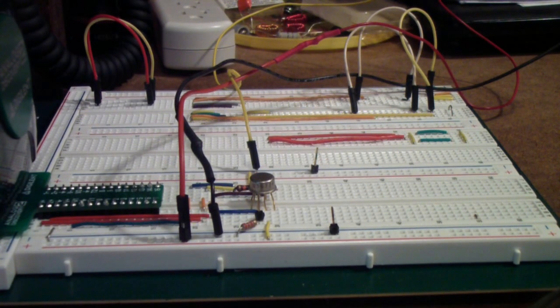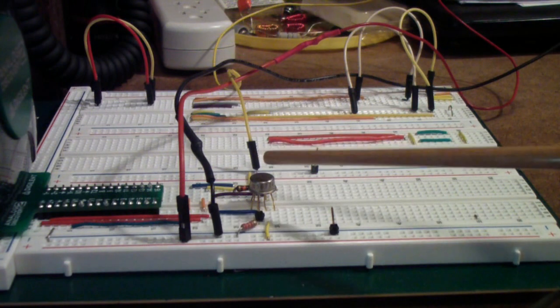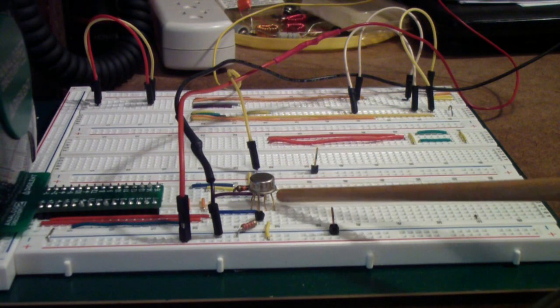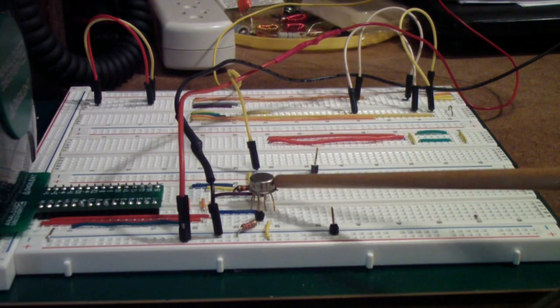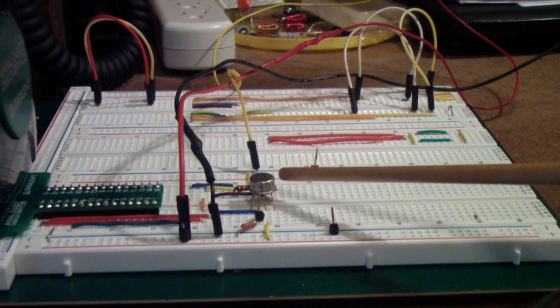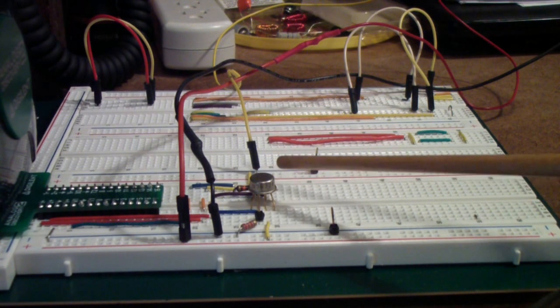So I hope using this old dinosaur, I'm not referring to myself, but I could be, helps you to understand that what goes on in an operational amplifier is sometimes determined by some circuit characteristics inside. In this case, the compensation capacitor limits the slew rate.